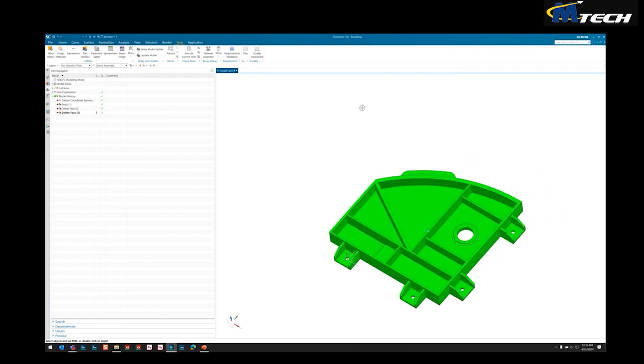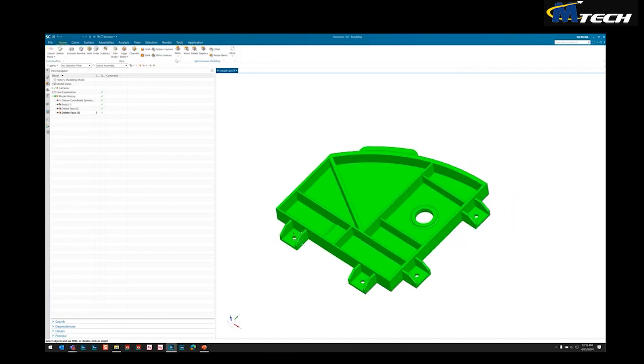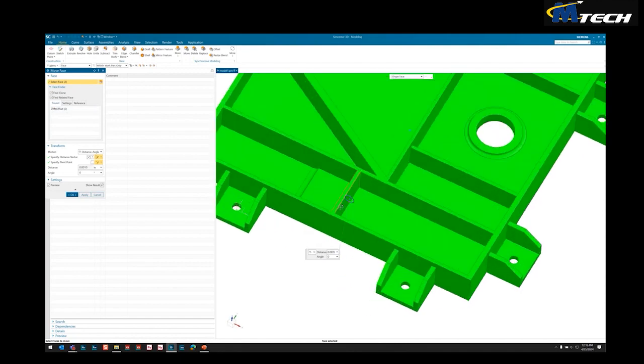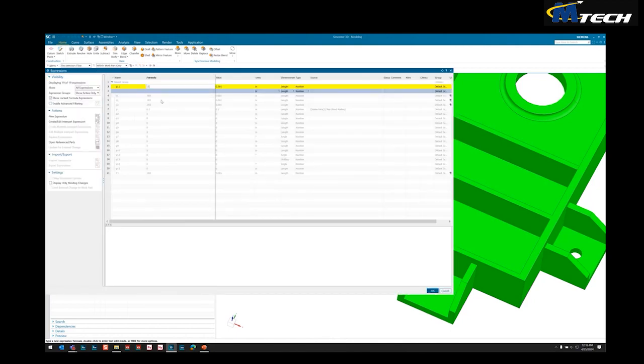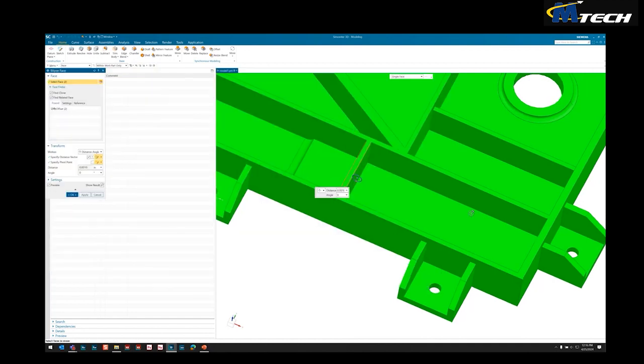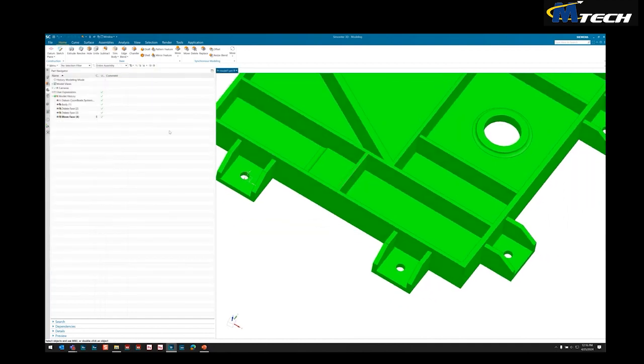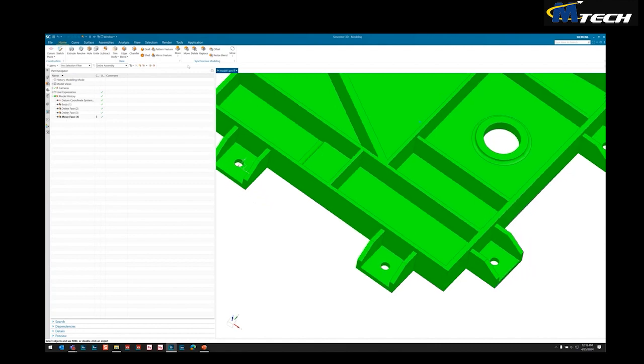So with synchronous modeling, you can move the stiffeners by both faces. You can see both of these faces are going to be offset in this direction by whatever value we choose here. This is going to be our first stiffener, so we'll set a formula equal to L1, first stiffener. And we'll hit OK. And you can see it's now building our feature-based history tree.